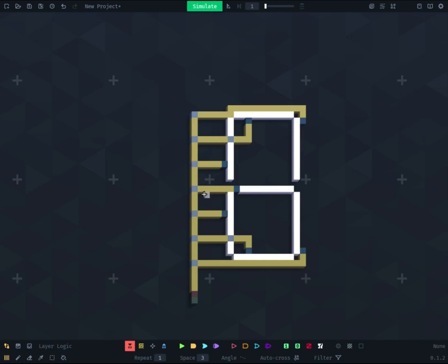For example, since each of these wires represents a segment, if we want to display the number 0, we do not want to have this segment lighten up. And if we use crosses, we are gonna have to specify which of these segments we're gonna lighten up. And if we do not use crosses, each of these would lighten up, and that's not what we want. So instead, we have to specify which one of these we want to light up. And we're gonna do that through using a buffer gate.